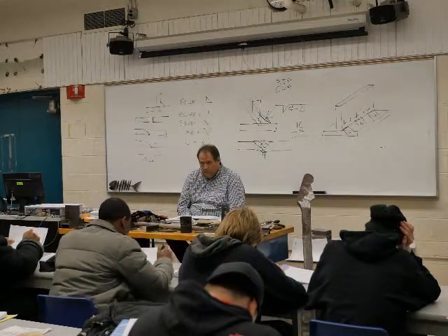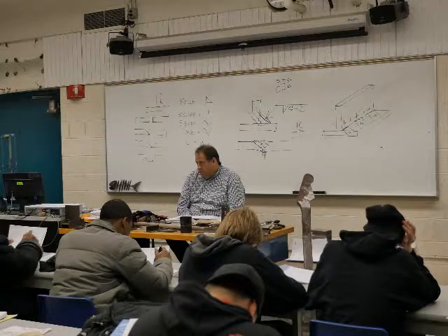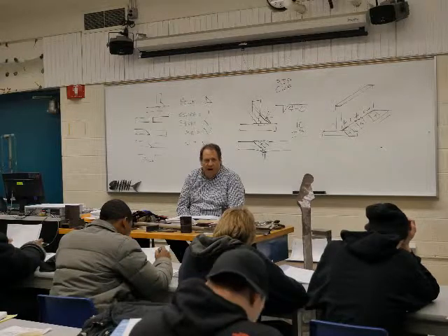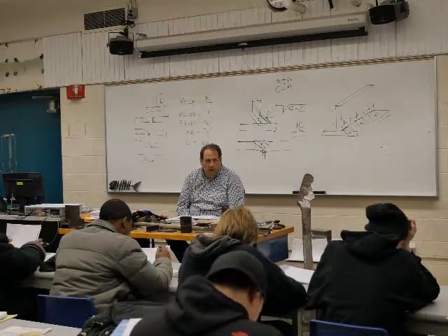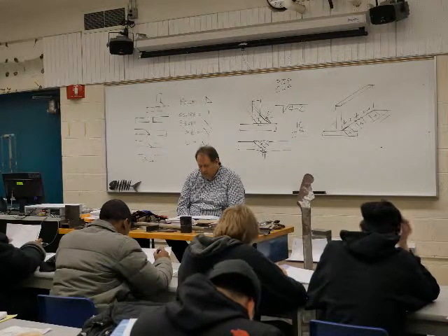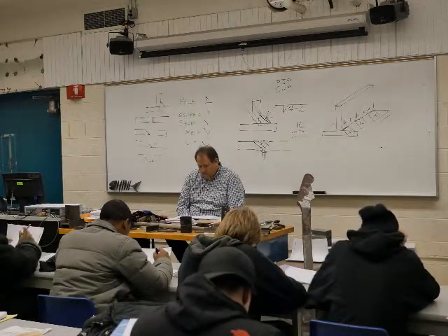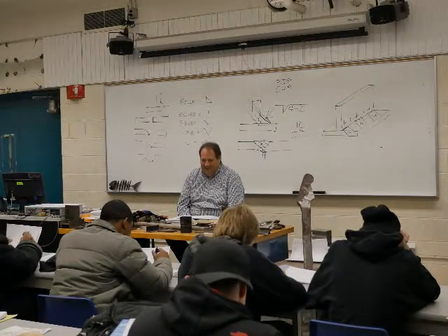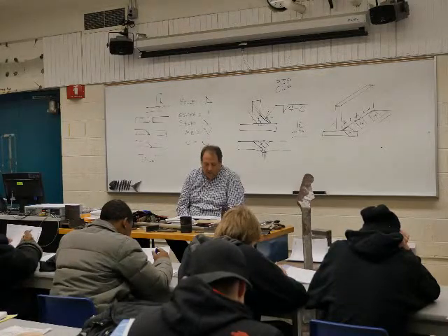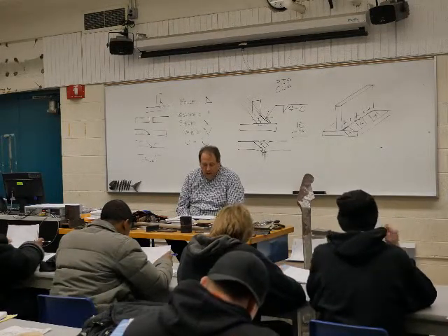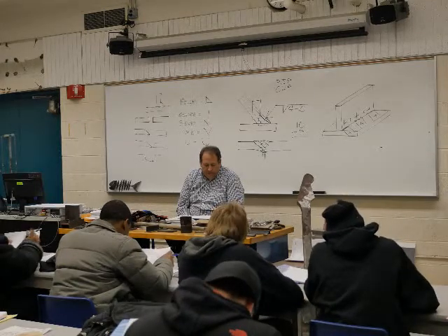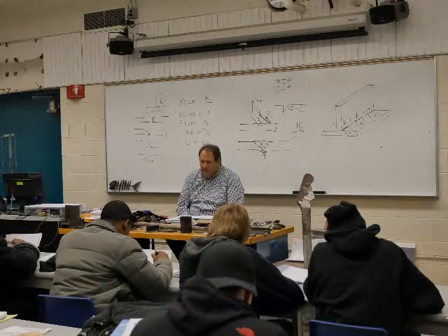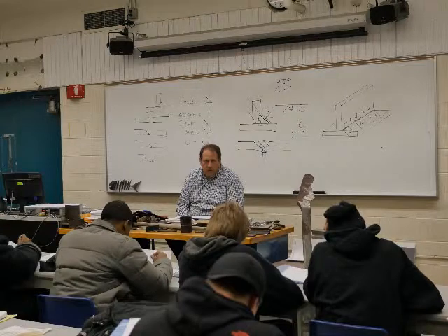All the weld symbols. 4. What do you got? You got 5? We got 4, we got 5, we got 3, 6. Are we sure? No. Okay, let's start with view X. First one from the left, 1/4 inch fillet weld, flat contour with a P. In this case we're not using a P finish symbol, so I don't know what this is.